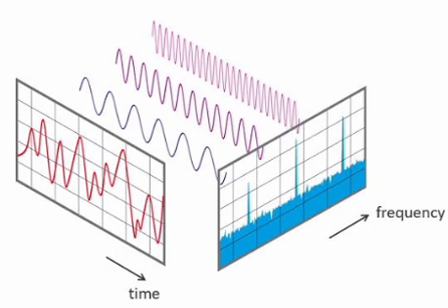Thus, x of n and X of omega make a Fourier transform pair: x of n discrete, periodic DTFT gives X of omega periodic, continuous. The inverse DTFT, which maps the frequency domain description X of omega back into time, is given as x of n equal to 1 by 2 pi integration over 2 pi of X of omega e power j omega n d omega.